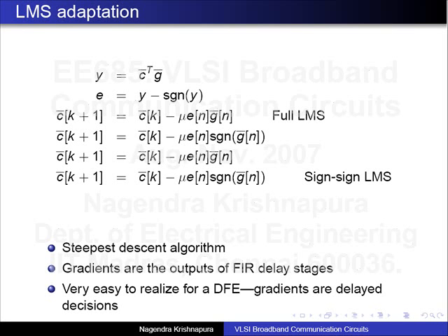The input signal is also noisy, right? The gradient is noisy and everything. Because of that, there will be too much chatter in the coefficients. And if you try to do it at very high speed, you consume too much power. So from both points of view, you don't update it every cycle. In fact, you update it infrequently, and in many cases, once the coefficient settles to some value, you just turn off adaptation and maybe restart the adaptation later when you need it.